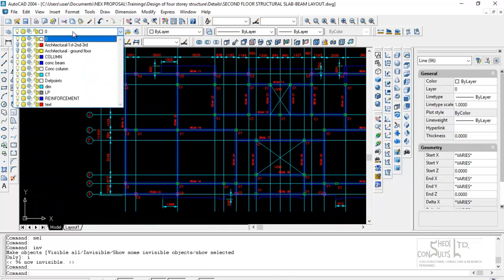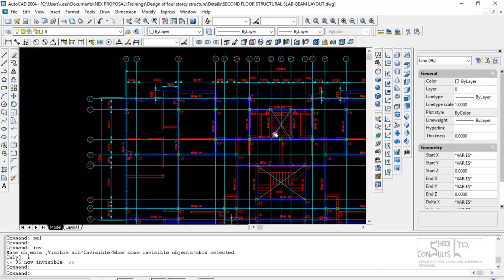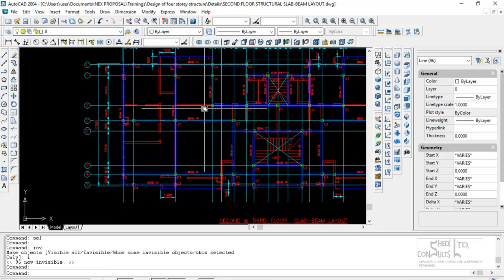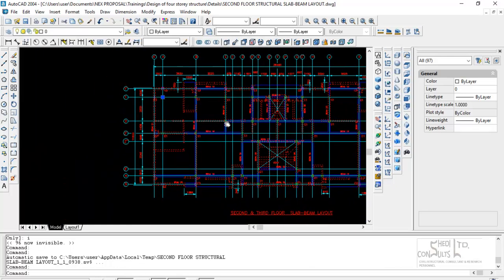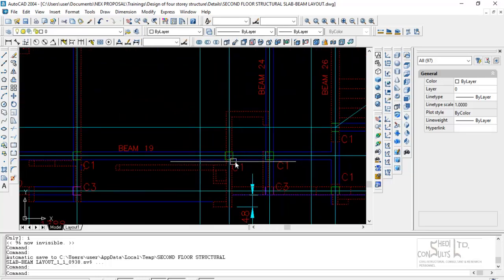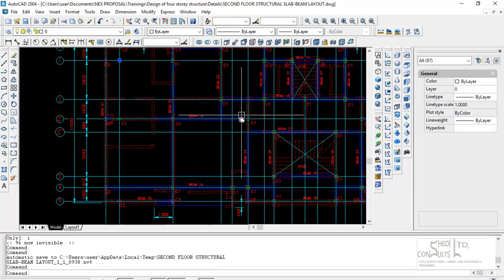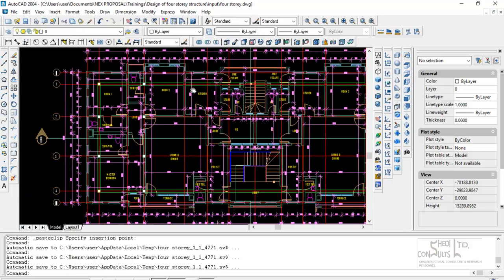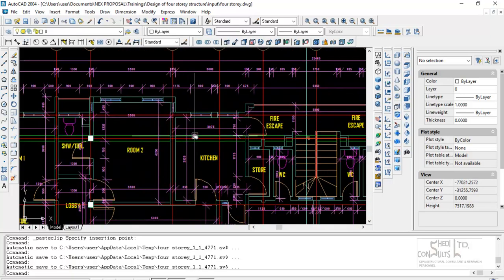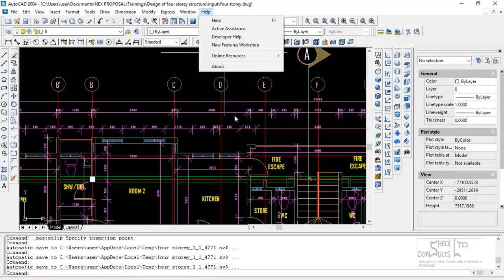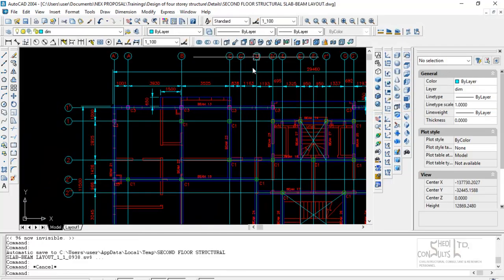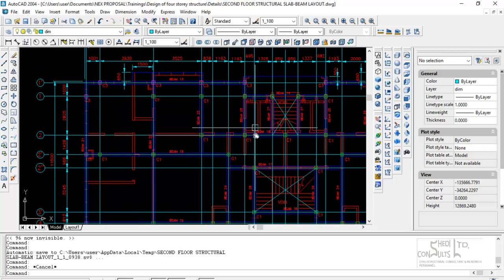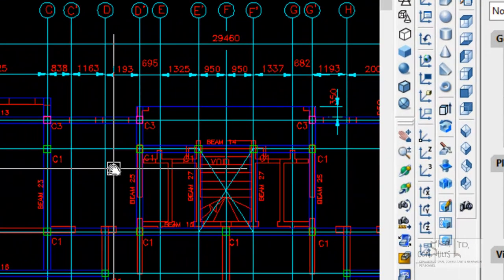If you reveal the second floor structural layout, let's see. You would see C, which is a grid on the architectural layout. That's C, and then C prime is a grid on the structural layout because of the column that we have positioned there. There is no C prime on the architectural layout. Okay, so it has C, which are the major 225 walls, and then you have D. So when we include a column, we identify that as C prime, or we include a structural element, either a beam or a column, as the case may be.